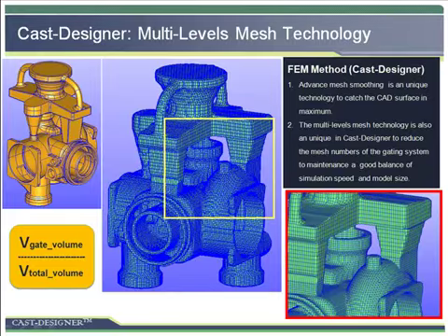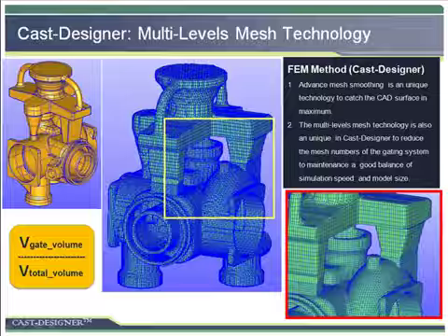Cast Designer developed a unique technology to generate a multi-level mesh for casting and gating. This is a breakthrough technology in the market today. With this technology, the elements in the gating and runner can be reduced around 4 times, and the result is still similar. The operation of such a multi-level mesh is very simple, only a few clicks, and suitable for any complex geometry.